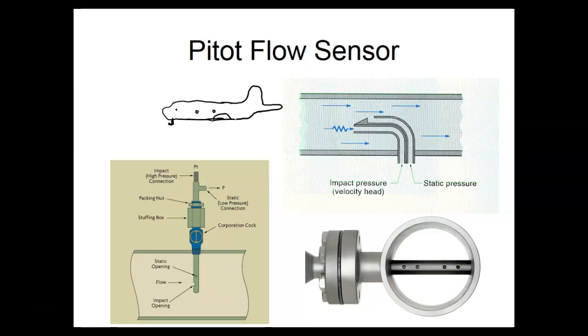I'm laughing because, you know, the Boeing 737, or whichever one it was, was crashing because of the pitot static tubes. They had a failure in the angle of attack sensor, which was basically the same thing. The angle of attack sensor had a little vane on it. Ours was mounted on the side of the plane, and the air flowing over it would tilt it depending on the attitude of the airplane. Boeing had a problem with theirs, and they did not have a backup system. So when it failed, it would tell the autopilot that was flying the plane.